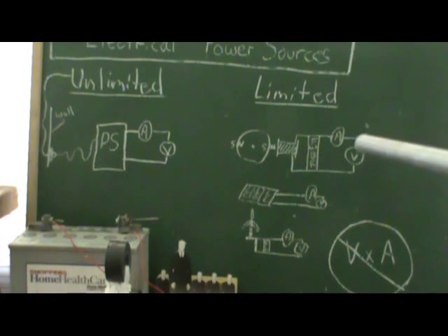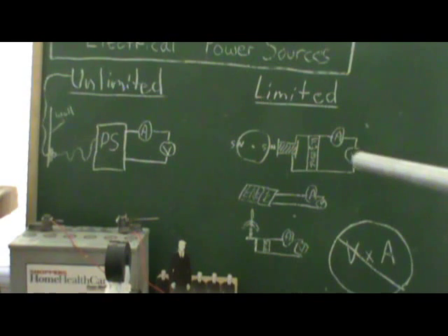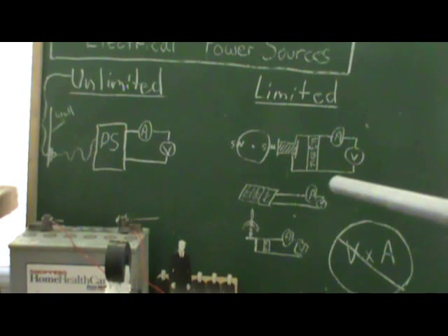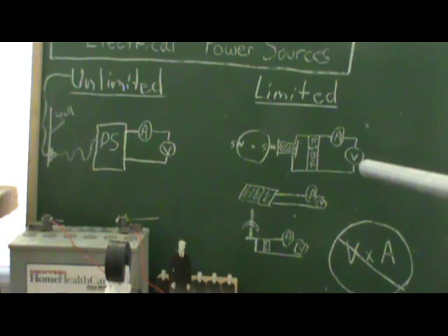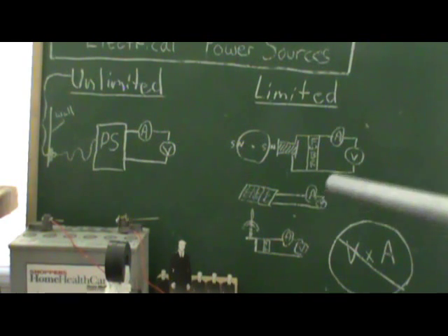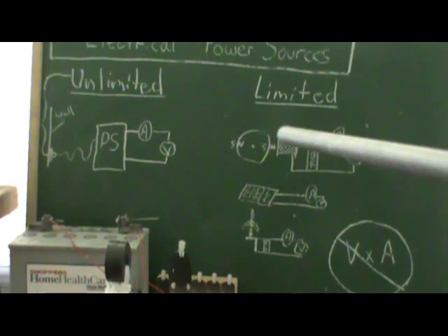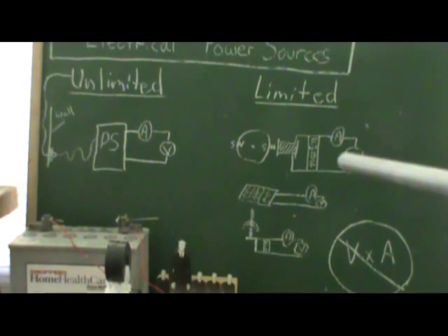When the load voltage approaches 0, let's say you don't have a 12 volt battery on there, let's say you have a half a volt battery on there, when you hook this up to your half volt battery, more current's going to flow through, and there's going to be less Lenz drag. You're going to really charge your battery really well.